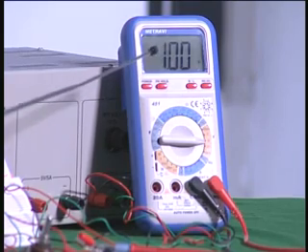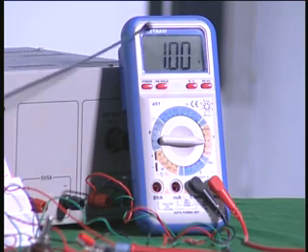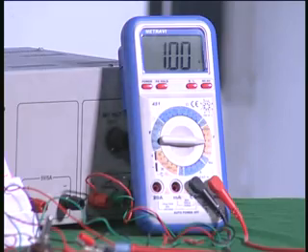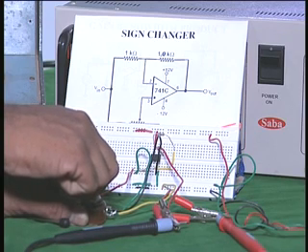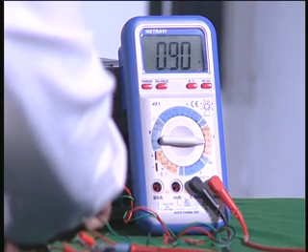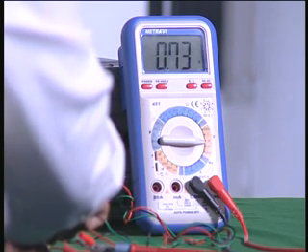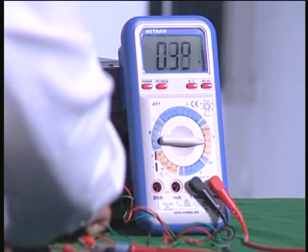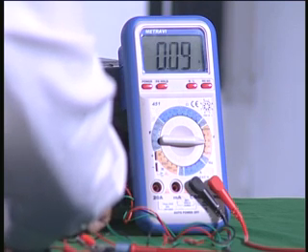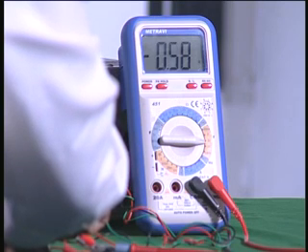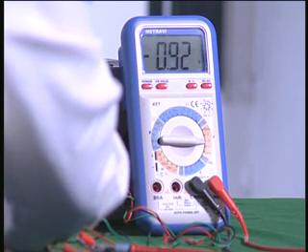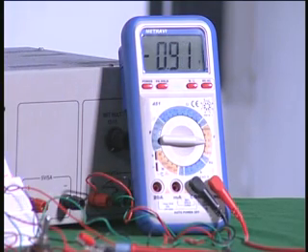When I change the potentiometer, this should go from +1 to -1 continuously. That is what I wanted to show. Please observe only the multimeter. I am going to now vary the potentiometer and see what happens to the gain. You see the gain now starts coming down. As I increase the potentiometer, the gain keeps coming down, the output voltage keeps coming down, and then almost I come to 0, and then as I keep increasing, the gain starts increasing on the negative side, -0.3, 0.4, 0.5, 0.6, 0.7, etc. When I go to the maximum, you find it has come again to nearly 1 volt, -0.91, which is closely -1 volt.